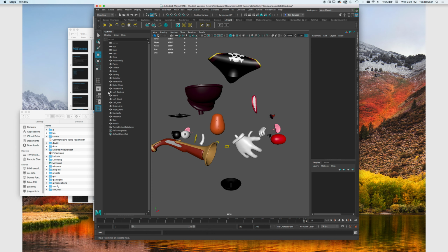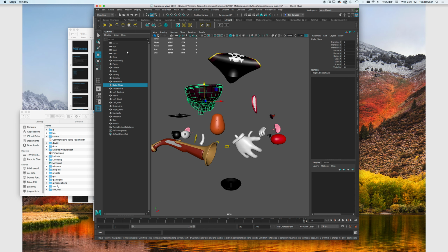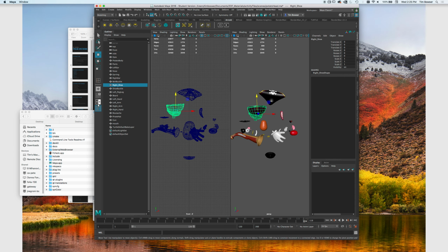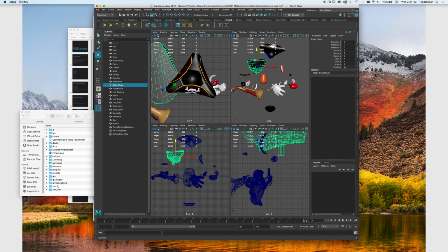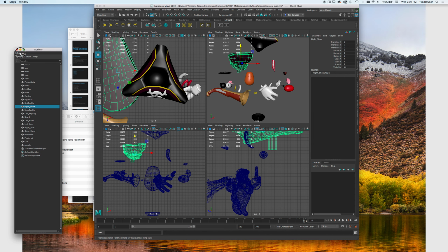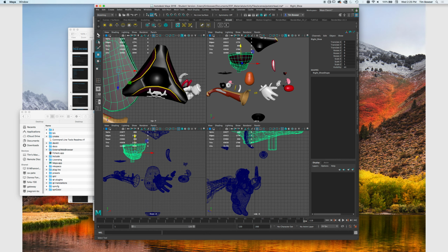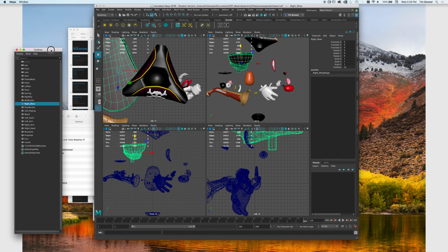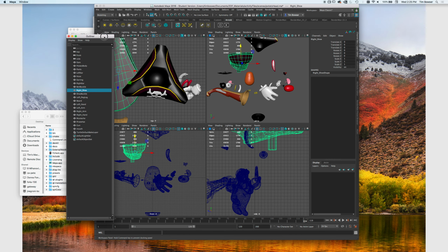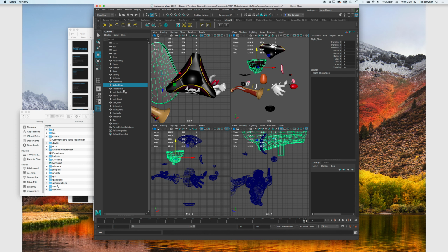I have my outliner on the left right here, which will allow us to get between kind of these pieces and parts. If your outliner is not on the left, what you can do is always dock it on your own. Any one of these menus you can rip off, you can close, and then for something like the outliner, I can go to Window, Outliner to open it, and if you grab the top, I can just dock it on the side there, right?